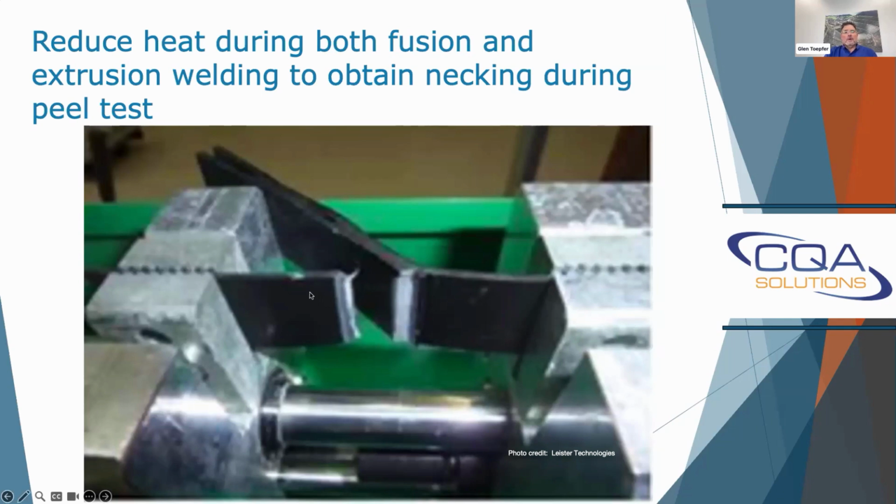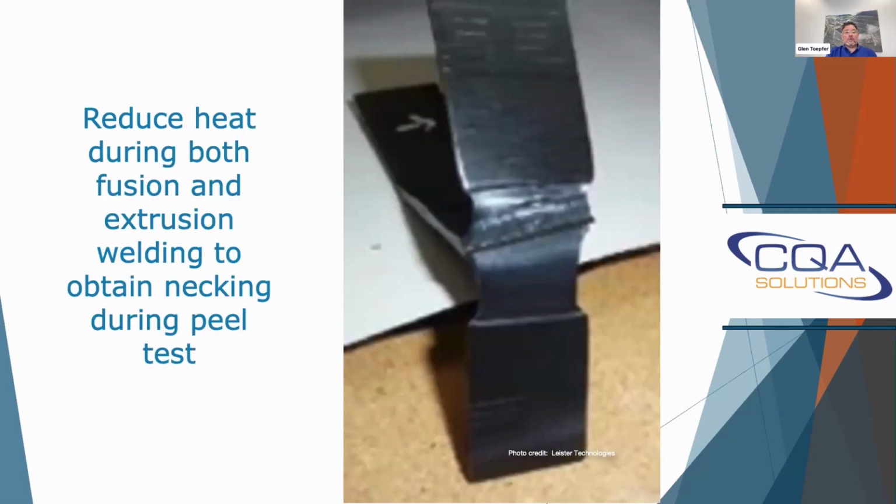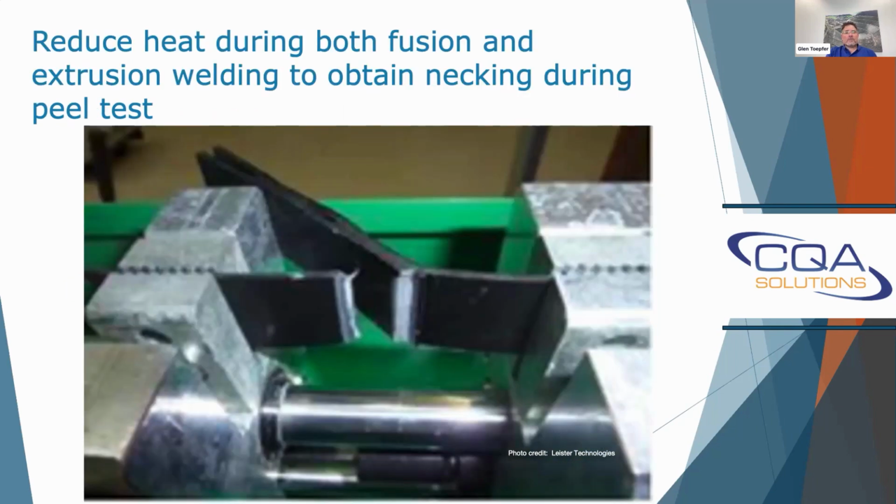And it's my belief, and the belief of others in this industry, that if we cool down the heating a bit, you can return to the necking that you're seeing on this previous slide without compromising the integrity of the weld and without compromising the integrity of the adjoining geomembrane. There are some installers, actually, I know, since I've been talking at conferences, who have taken it upon themselves to cut back on their heat a bit. And I haven't talked to them recently, but I know they were doing that.